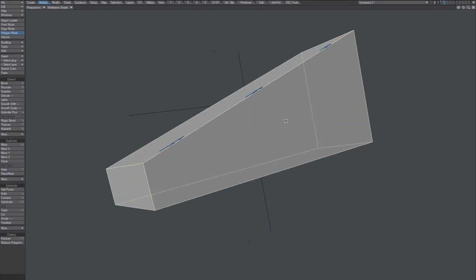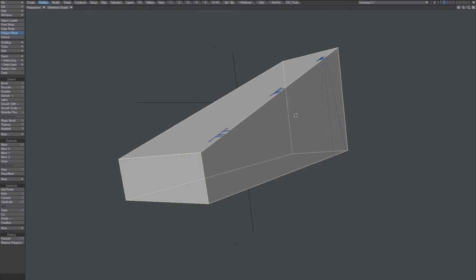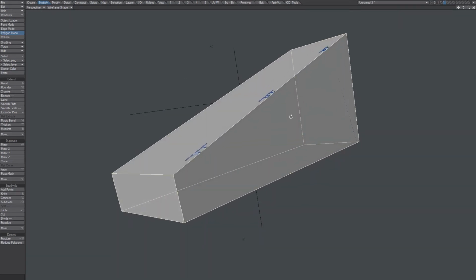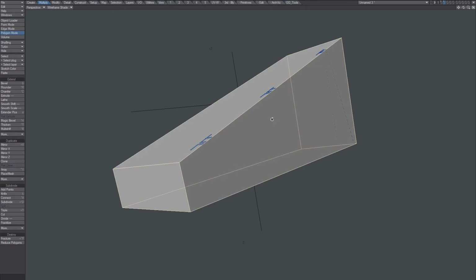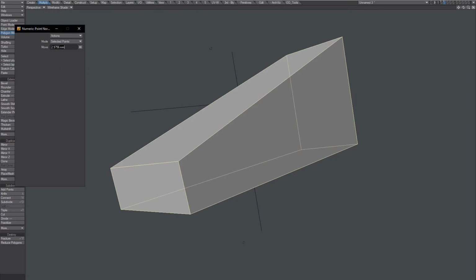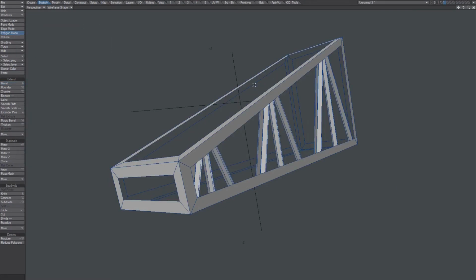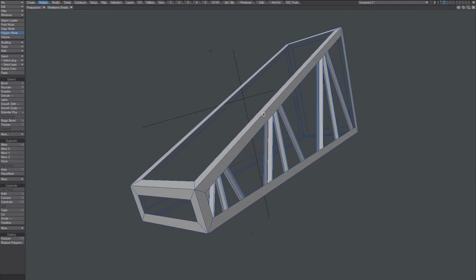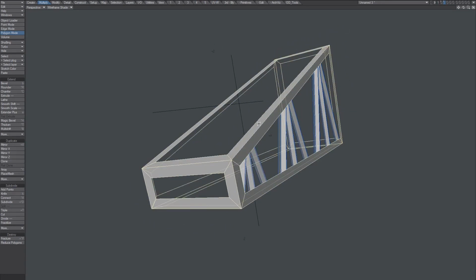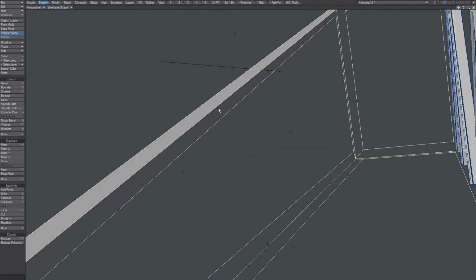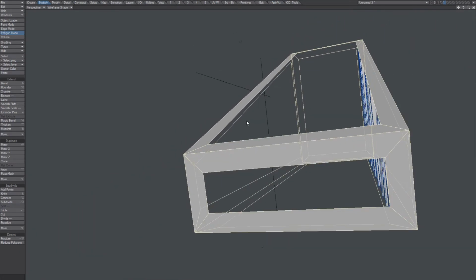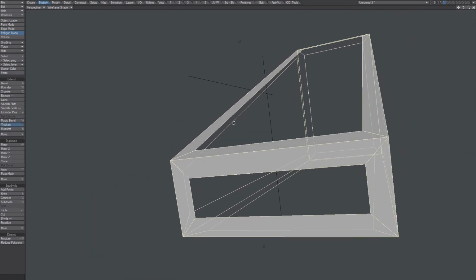Honestly, I think one of the smarter ways is just to do that at first. So just move that a touch up at first, like 3 millimeters or so, point normal move, and then bevel it as before, and then delete. Then you don't have that problem. And of course, this then can be thickened. I think that should work fairly okay. Let's see. Thicken. There we go.